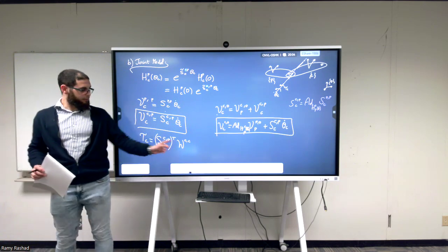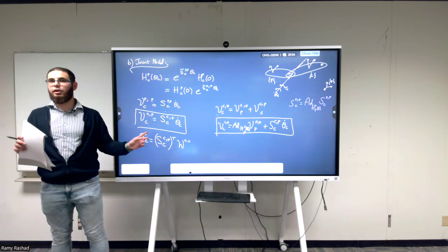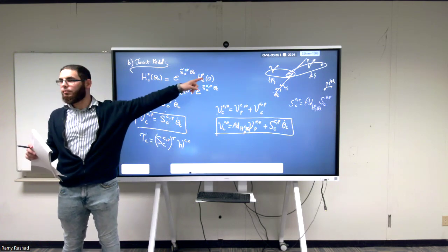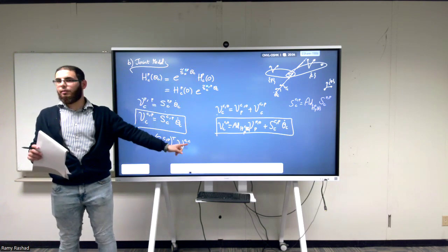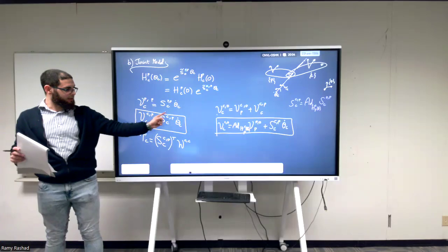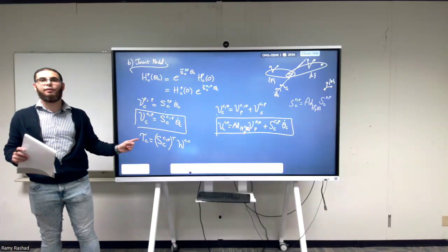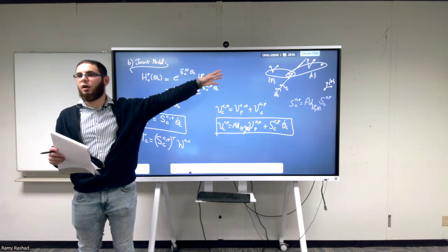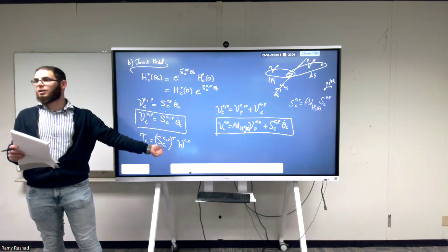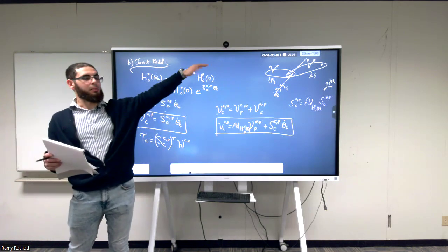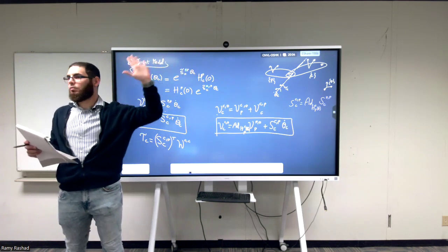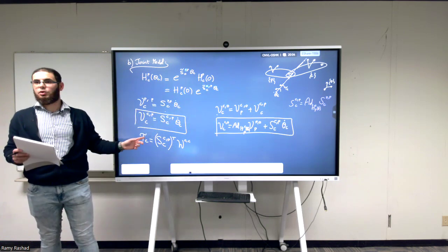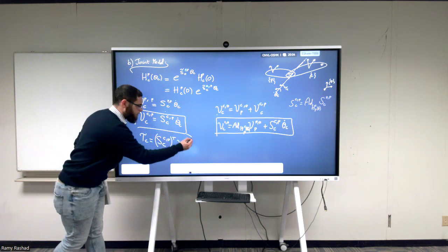So this is for any wrench. This is very important. This equation is for any wrench that you have applied on the C body, expressed in the C frame. If you multiply it by the transpose of this screw axis, it will give you whatever torque this wrench corresponds to. For example, if I have a wrench due to gravity, and I want to see the corresponding torque due to gravity, I multiply it like this. If I have some wrench due to interaction with the environment, and I want to see the corresponding torque, then I also use this expression, and so on. So this expression is simply the dual of the one on the top.